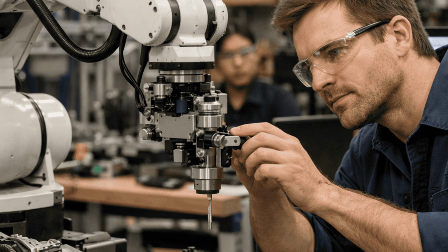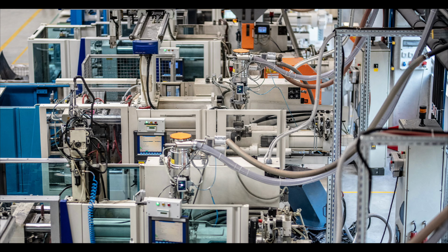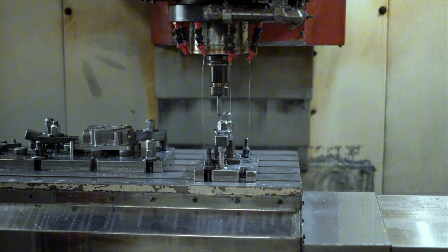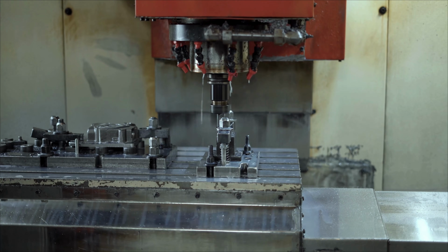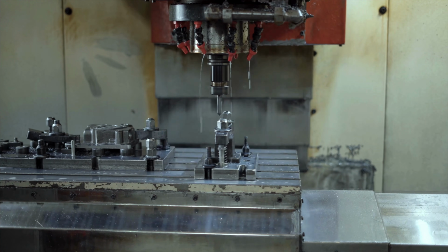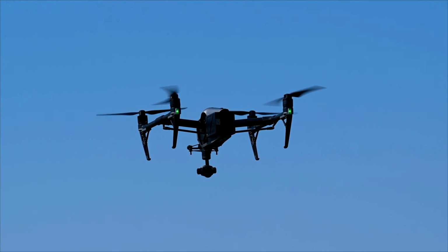However, in this modern world, engineers happily accept the best of both worlds, and hybrid systems seamlessly combine cams with software. Programmable logic controllers are often paired with cams to set a baseline timing, but then have a software layer for remote overrides. The CNC machines I mentioned before that use cams for tool swaps, there is a layer of digital control as well. Cams are used when an engineer wants a machine that cannot forget what it's supposed to do. Software is used when you want a machine that can change its mind.